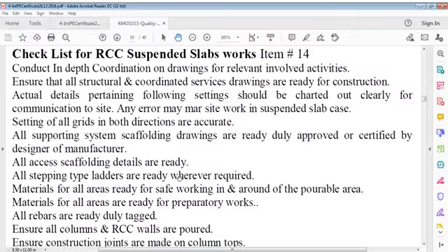Formwork is a preparatory activity and steel placing is a preparatory activity, but steel shall remain there forever, therefore it is permanent. All inserts, electrical, mechanical, or services are permanent because they shall remain there. Shuttering shall be taken out.